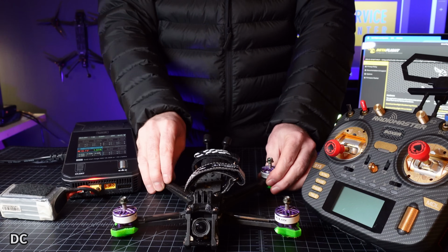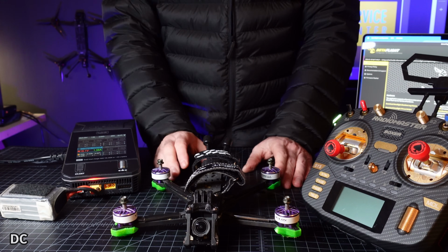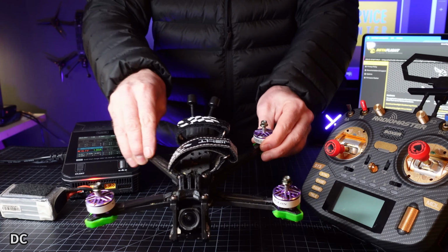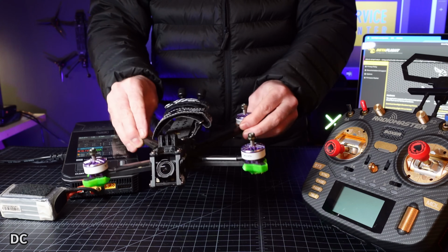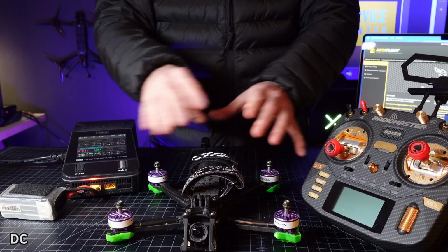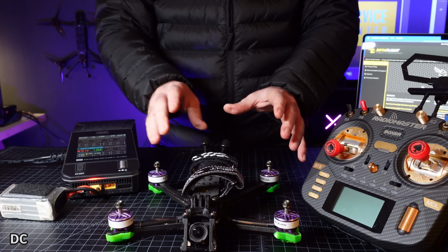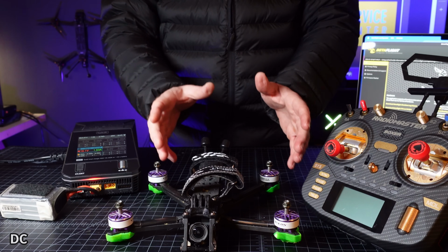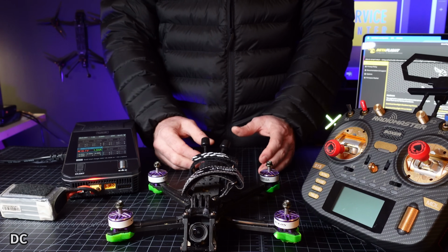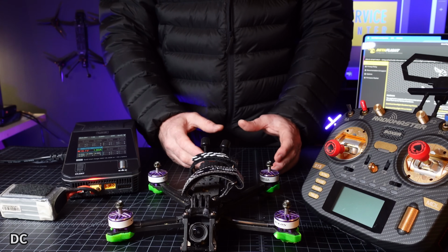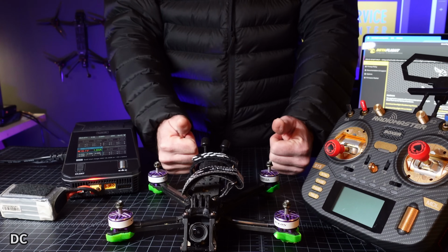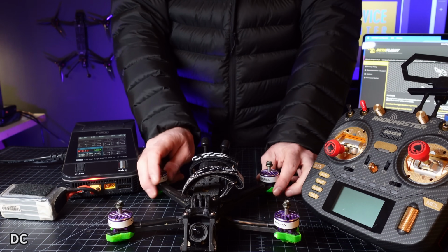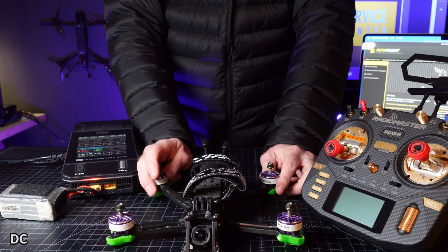And you know, what I do is every single day I get new drones here on the channel all the time. So what I do is I test hover it, I make sure it goes forward, back, left, right. All my axes are good, propellers, everything is good, motor direction's good. So that's what you're testing on that first initial flight. Doing it line of sight, it just lets you know while you're not goggled up that things are not going to go wrong. Once everything is good from a line of sight flight test, I will go ahead and I will goggle up, and then I will fly it after that.